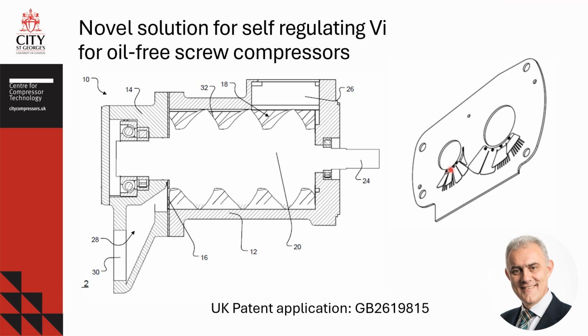Individual discharge valves are activated when pressure in the compression chamber rises to a sufficient level to push a valve into the discharge plenum, while other valves remain closed where that condition is not fulfilled. This self-regulating system ensures that the volume index is changing by the demand of an application. Such systems can also be applied to oil-injected screw compressors.